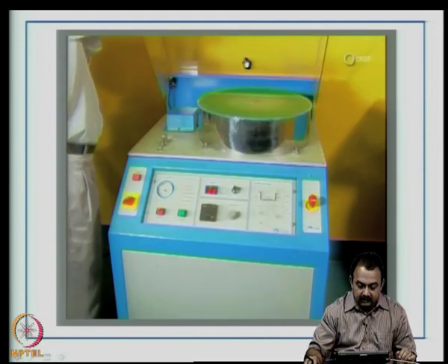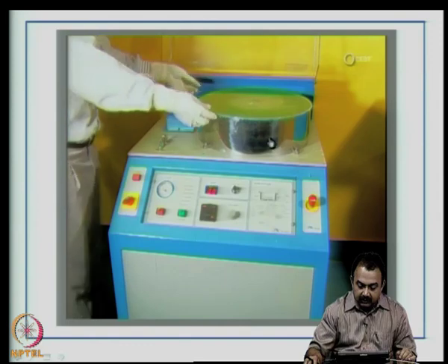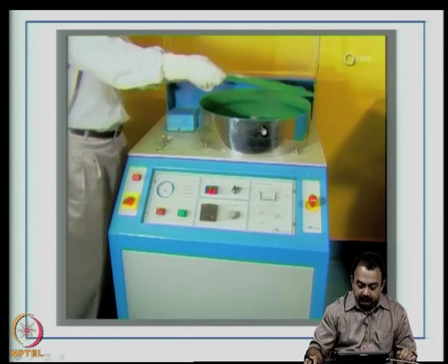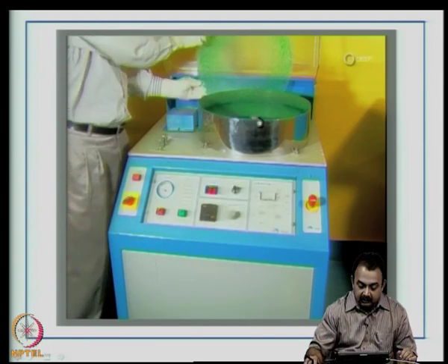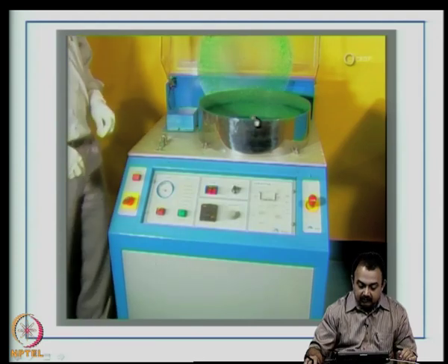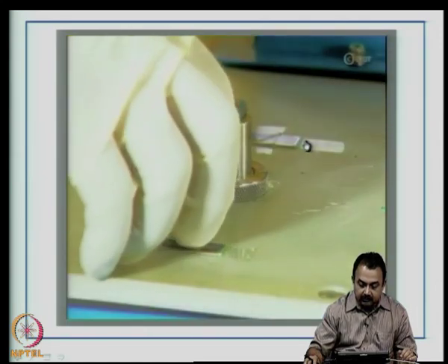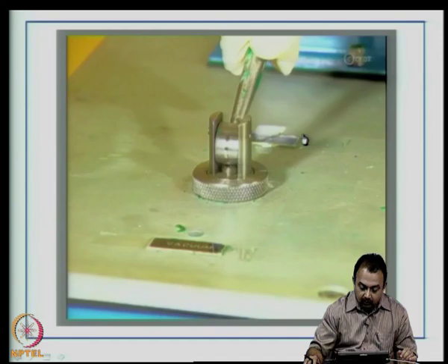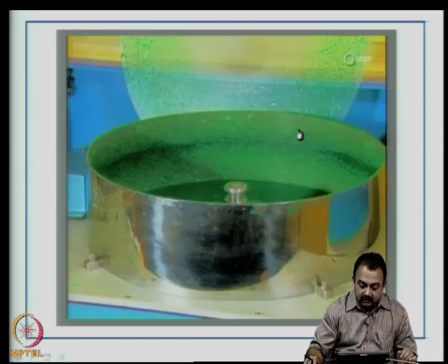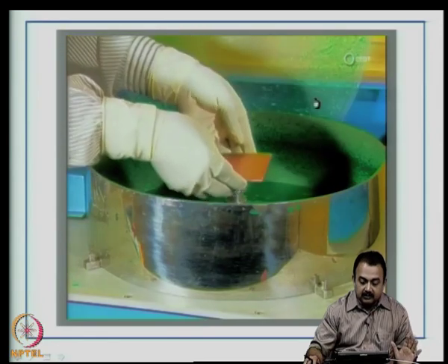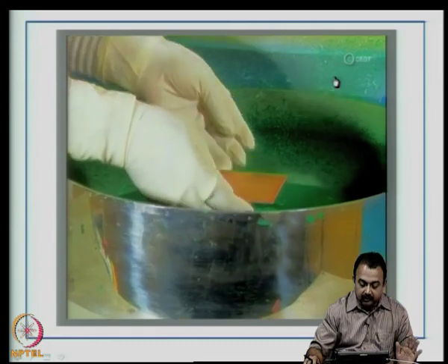You can see here it has a protective lid, then there is a cover which is protecting the all important spin coating area. There you can see a chuck at the center which will hold the substrate. Now, this equipment has provision for vacuum hold of the substrate. So, currently the vacuum is released. The substrate is well prepared, that means the surface has to be very clean. In order to avoid de-wetting, there should be very good wetting.